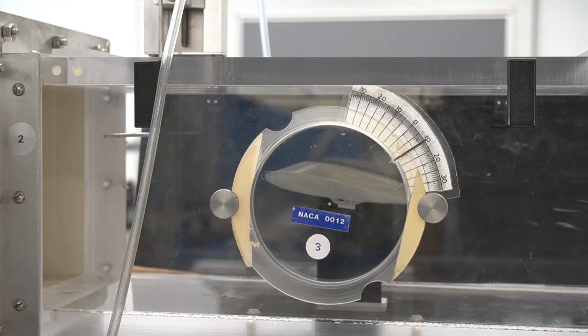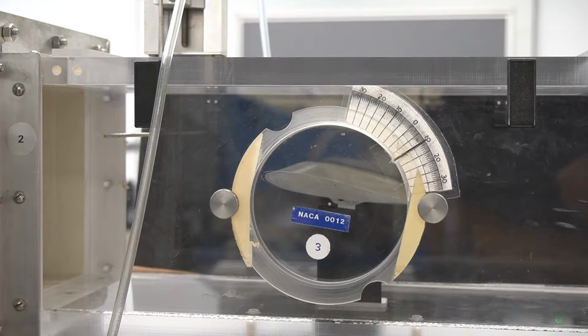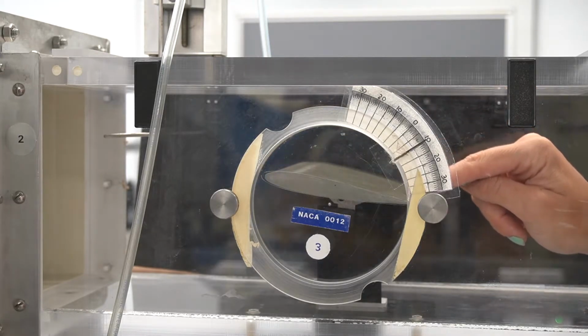Okay, so Jay, can you tell me a little bit more about how this partial stall regime works? Right, so for attached flow, if we look at the flow of the airfoil, the flow itself stays attached from leading edge to trailing edge, so it does not detach from the body of the airfoil. But as we enter partial stall, we start getting separation. And so the separation starts at the trailing edge. So it starts back here?